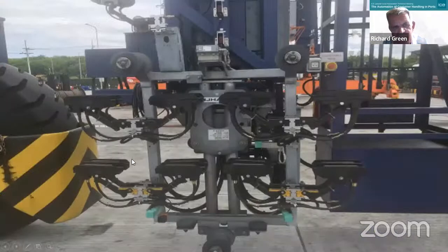Here's a side view. These are the connectors that pick up the power supply. These are the Diablo rollers. There's one down here, two up here. And this is how we bring the RTGCs onto the power supply. The RTGCs have small donkey engines, a small diesel engine, so that when they have to go from one stacking area to the other, they lose the contactors. They can just maneuver across the access road under their own steam by a small diesel engine.